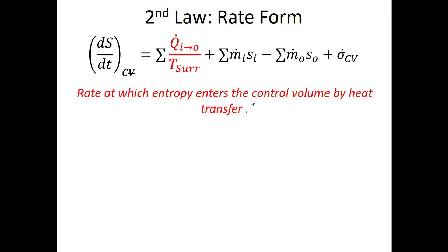So here, does it say it's an isentropic or an ideal pump? Maybe I missed that. Yeah, it's an ideal pump. So for an ideal pump, the temperature at the inlet of the pump is equal to the temperature at the outlet of the pump. There are a lot of red herrings in here. You might be like, oh, I'm going to try to find the ideal power that the pump consumes, or maybe I do a second law analysis or something. But all you have to know is what's the temperature at the inlet of the pump, because across an ideal pump, we assume that the temperature difference is 0.